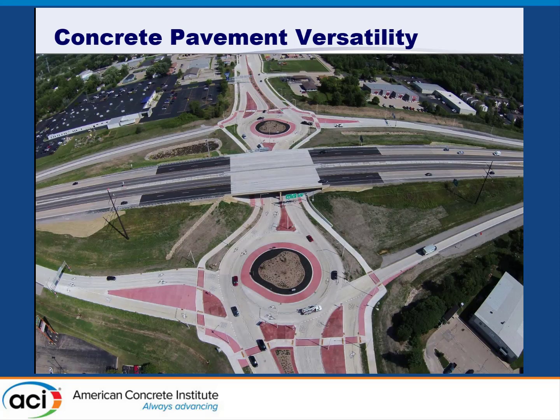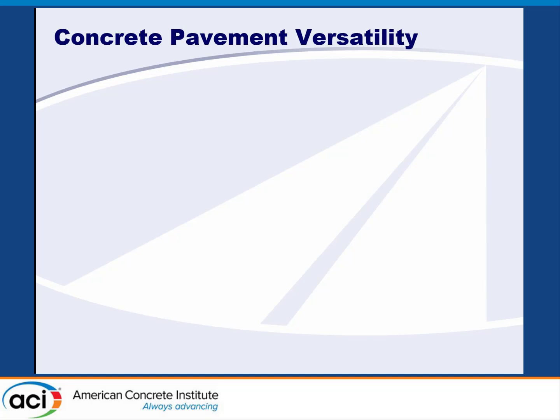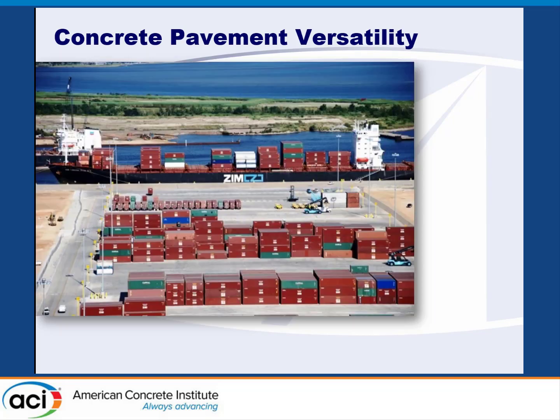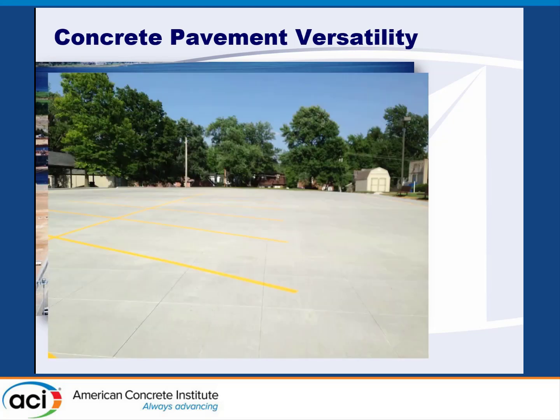And we have intersections. We also have roundabouts. So roundabouts are another big place where we're considering how the pavement is going to be reacting to our loading scenario as well. But in addition to those full depth and overlay type concepts for concrete pavements, we also have other types of facilities that concrete can be utilized in. Those site paving type facilities, industrial pavements, heavy trucking facilities, all can be designed with concrete and built with concrete. We also have parking lots where we're typically seeing just smaller, lighter traffic.